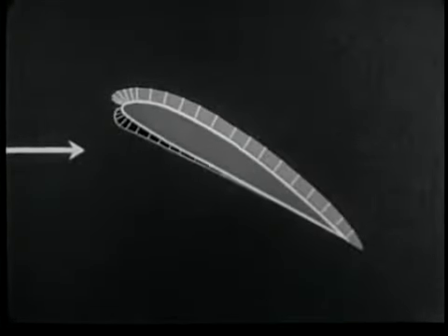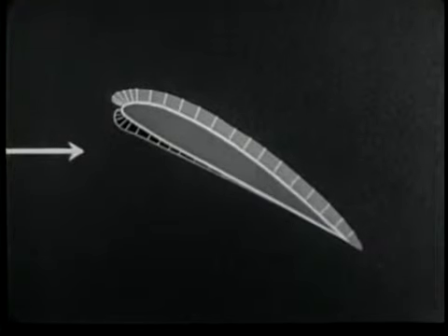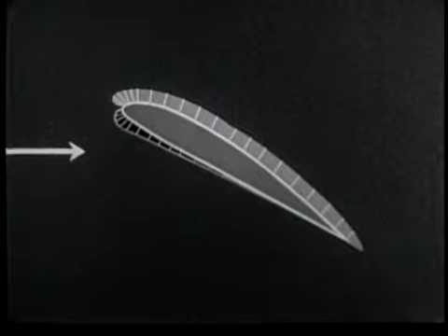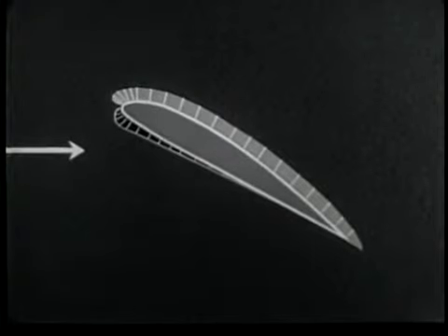At this angle of attack, the forward protuberance disappears completely, and an area of nearly equal negative pressure blankets the entire upper surface of the wing. Positive pressure areas still show no important change.